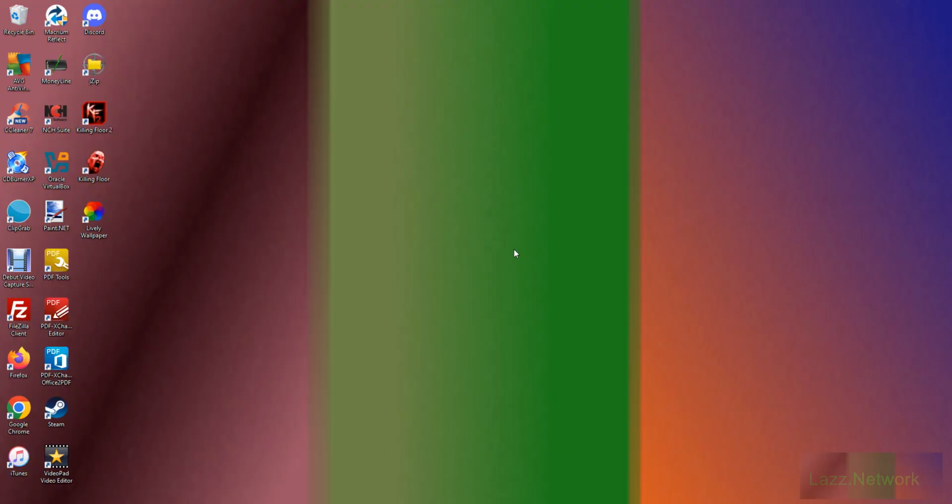You test everything for this. The difference being is that for your actual hydrometer portion of your test, you're only testing material either passing your number 4 sieve or your number 10 sieve. And that's kind of the optional thing. But it also depends on your test method too. I don't want to dig too deep.